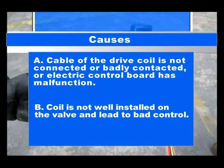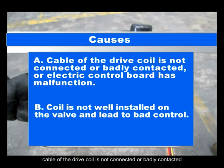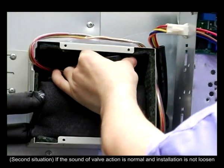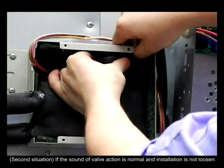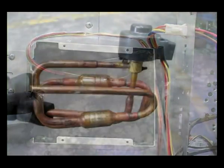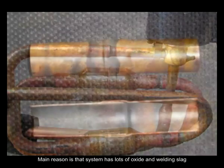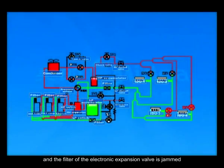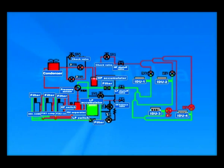Causes: the cable of the drive coil is not connected or badly connected, or the electric control board has a malfunction. The coil is not well installed on the valve and leads to bad control. Second situation: the sound of valve action is normal and the installation is not loose. Causes: the main reason is that the system has lots of oxide and welding slag, and the filter of the electronic expansion valve is jammed.